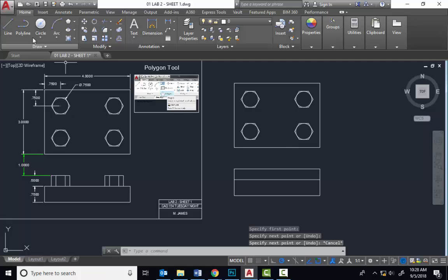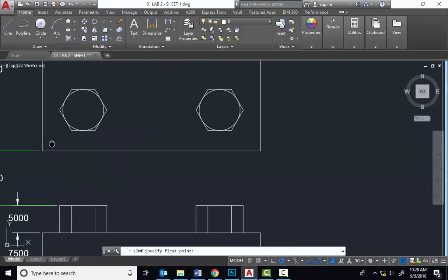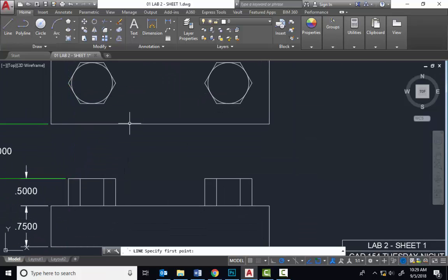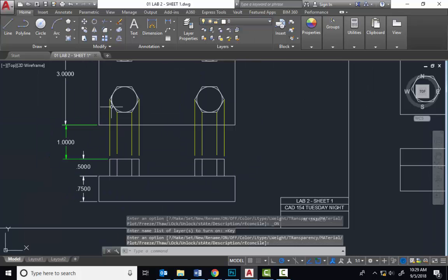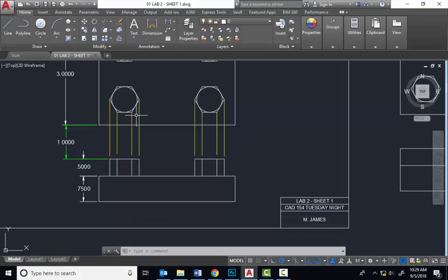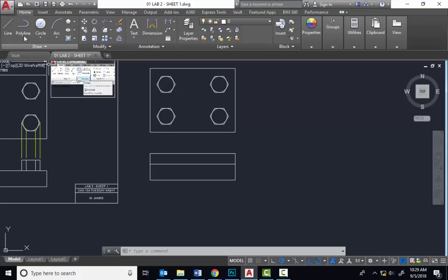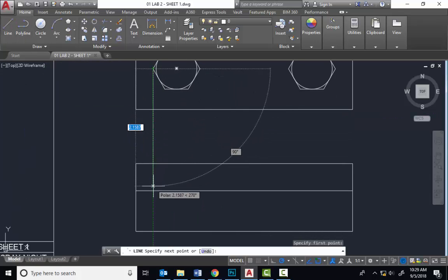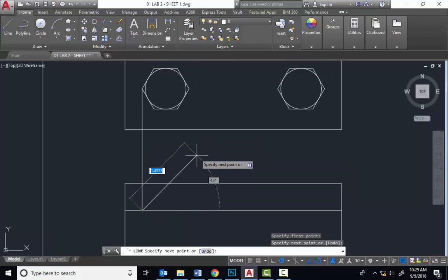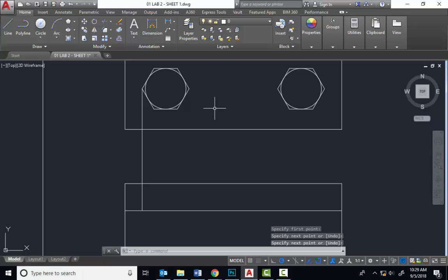Now, this is new. We're going to grab the line, and these actually drop down from the top down. Let me show you. If I turn on this little key thing, see how from this corner you drop it straight down, straight down, straight down, and so on? Watch. Line tool. Make sure you click on the correct thing. With my left hand, I'm going to hit enter to finish it. And if I hit enter, it's going to repeat my last command. So enter to repeat the line command.